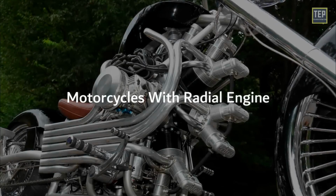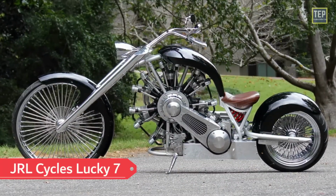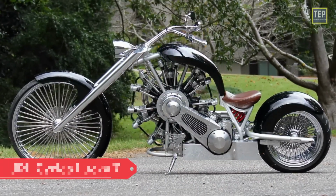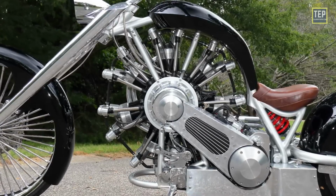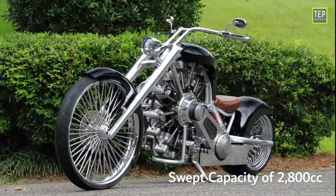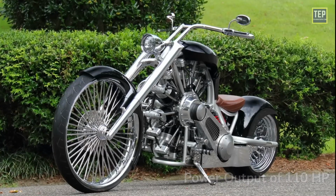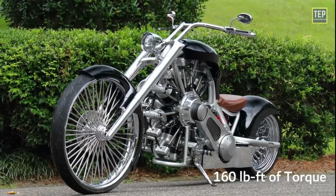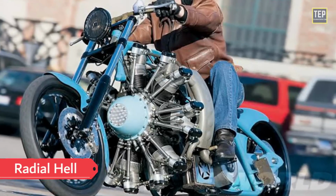Motorcycles with radial engine. For a brief time, the JRL Cycles Lucky 7 was the only radial engine production motorcycle in the world. The engine is powered by an Australian-designed and built 7-cylinder radial aircraft engine with a swept capacity of 2,800 cc and a power output of 110 horsepower and 160 foot-pound of torque. Radial Hell is another bike with radial engine.